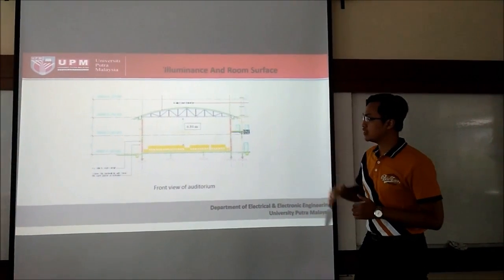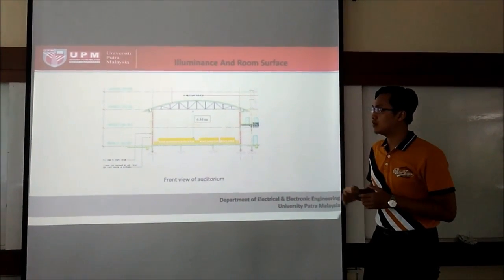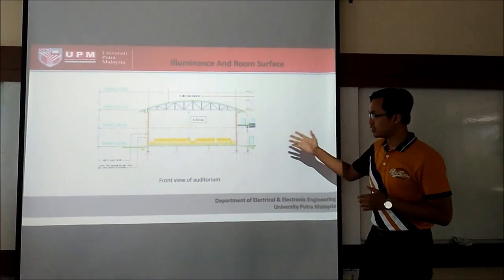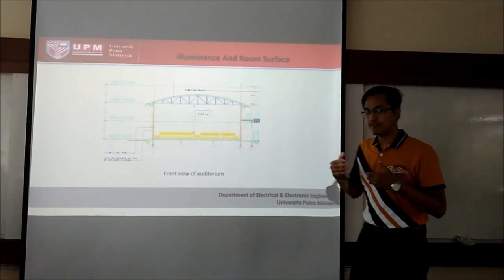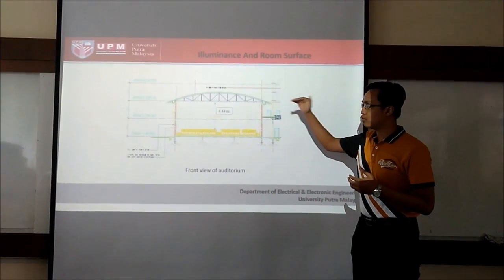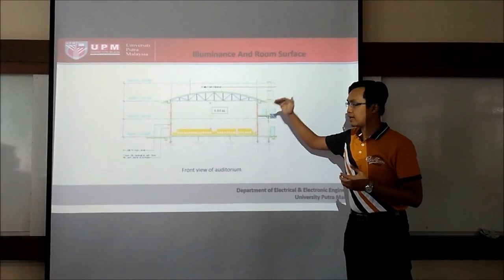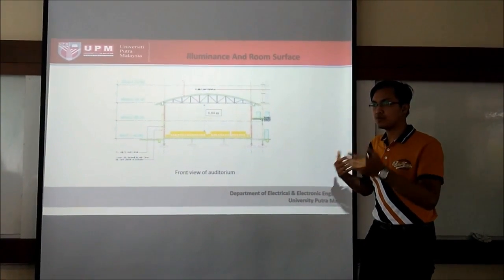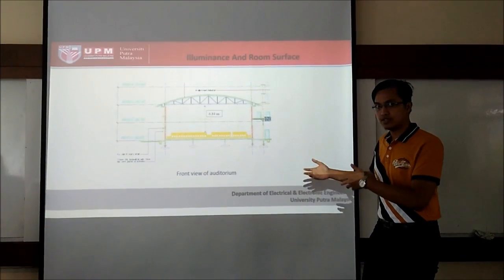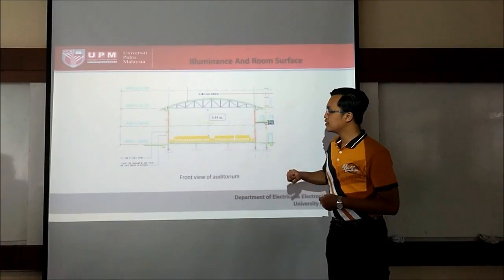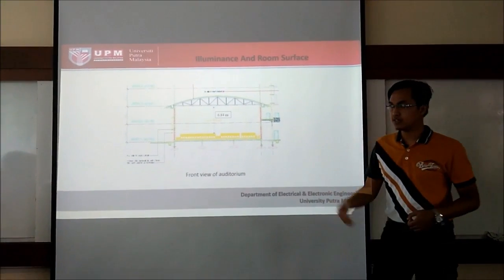Basically, this is the front view of the auditorium. We need this view because we want to find out the height between the luminaire and the workplace. After we study this room, the height is 6.84 meters.